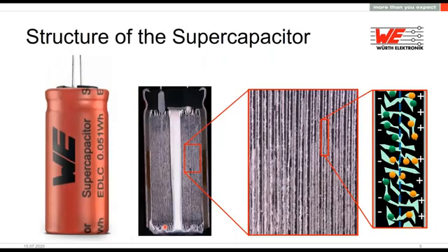But let's go back to the supercapacitors, and try to answer some questions like how the electrodes of an EDLC look, how we can get this large effective area, and also what the Helmholtz layer is. The Helmholtz layer is an electrostatic storage of the electrical energy by separation of charge at the anode.